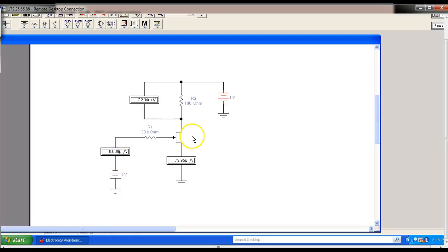And when we did the bipolar junction transistors, the collector characteristic curves varied with a slant. These guys are almost parallel with the x-axis. I get those confused all the time, which is really neat. So above pinch-off voltage, you're controlling this with the gate to source voltage.